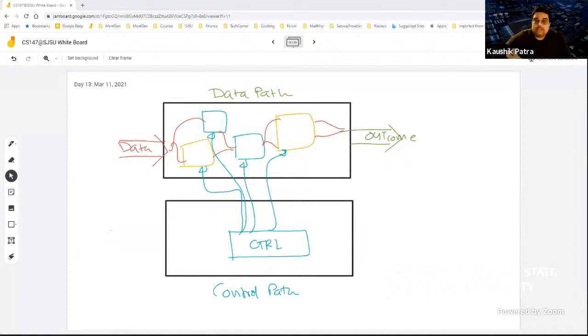In the I-type instructions, we'll also see a similar approach. But I-type instruction data path design is more complex because almost each instruction has a different data path. We cannot just classify like the R-type, saying this is arithmetic and follows a similar data crunching route, versus this is a logical operation and follows another route, and so on. It is not simple like that. Almost each separate instruction has its separate data path. The only cluster is the arithmetic immediate operations and the logical immediate operations.